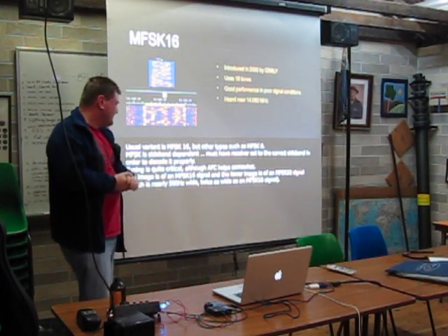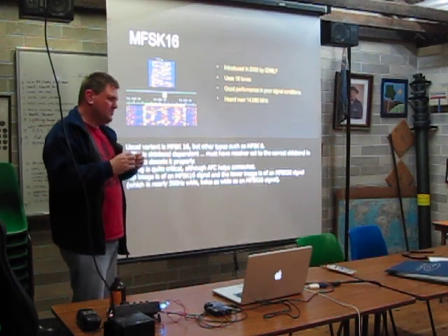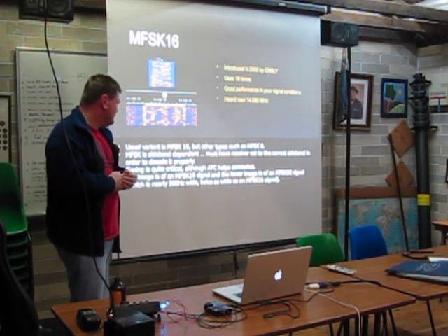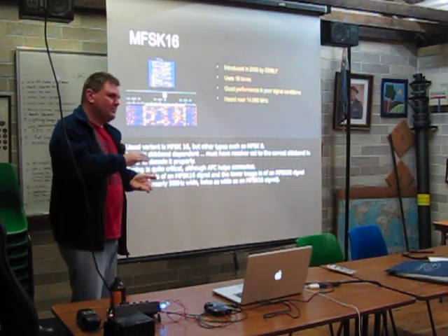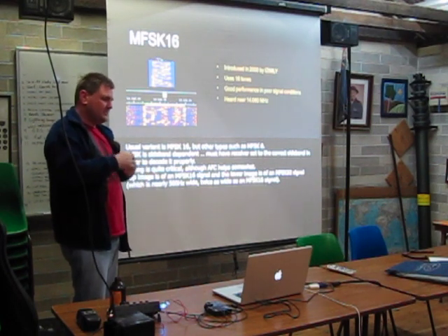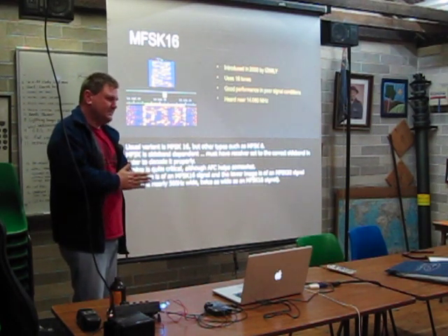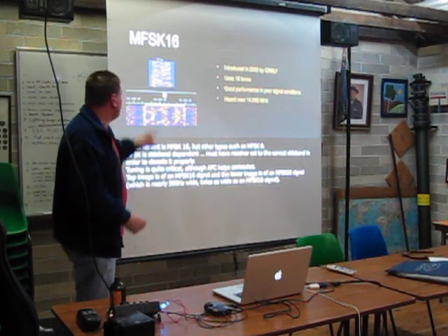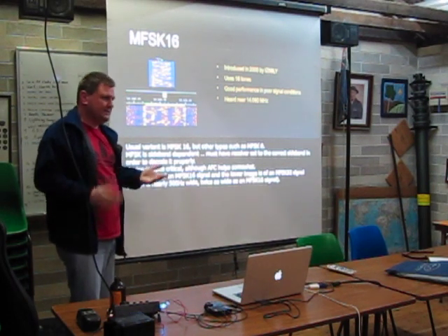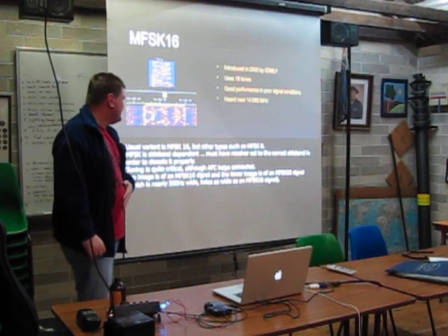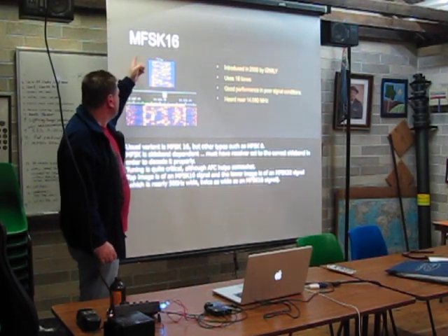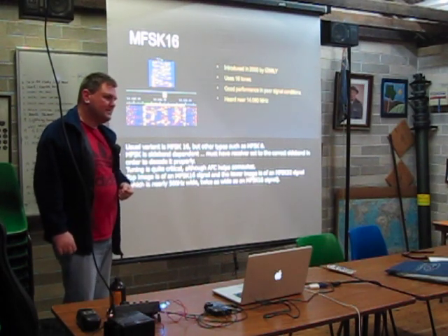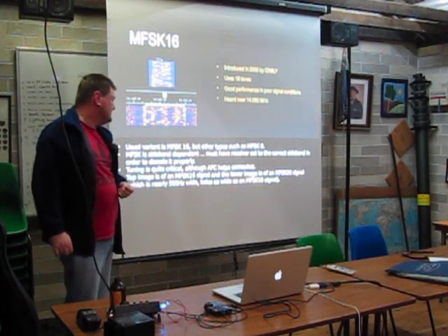The other thing you can do is if you're able to send more information, you can send more redundant information which has error correction. So if the signal quality is poor, then because you're sending a lot of redundant information, the receiving end is more likely to be able to pull the signal out of the noise. So on the HF bands where you've got lots of static and fading and multipath, things like that, multi-frequency shift keying is probably one of the better communication modes when you're dealing with poor quality signals.